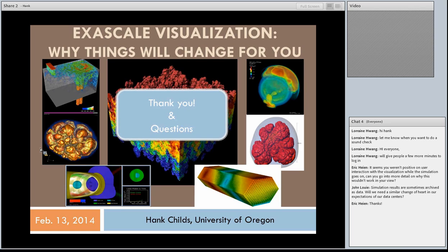I think so. I think this is another axis that we're going to have to give a lot on, and I think this is something that probably people on this call know pretty well. You run a simulation on one machine, and maybe the disk is pretty good, and so you save out a snapshot in time of your simulation every 100th cycle. But then you go to another machine where the I/O subsystem isn't good, and gosh, you could find that you're spending almost all of your time doing I/O. So what do you do? You maybe save out less frequently. Maybe you save out every 200 cycles.